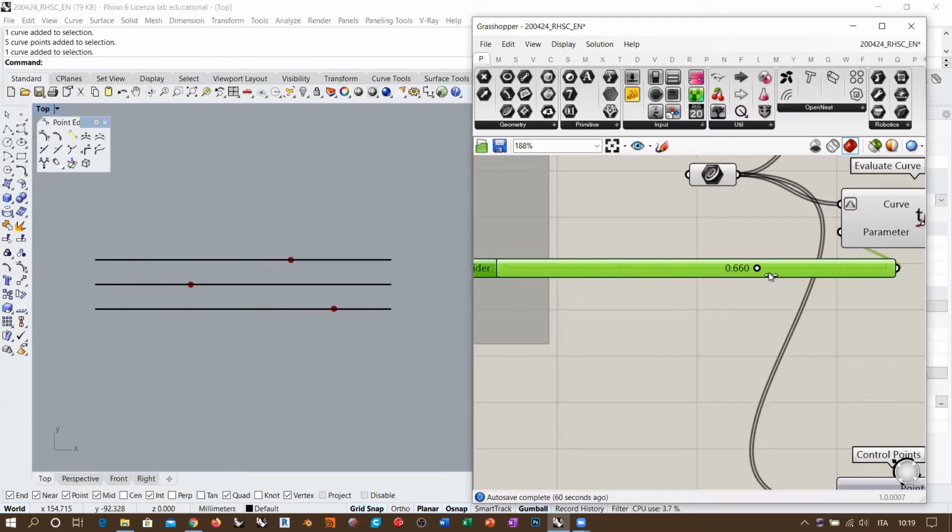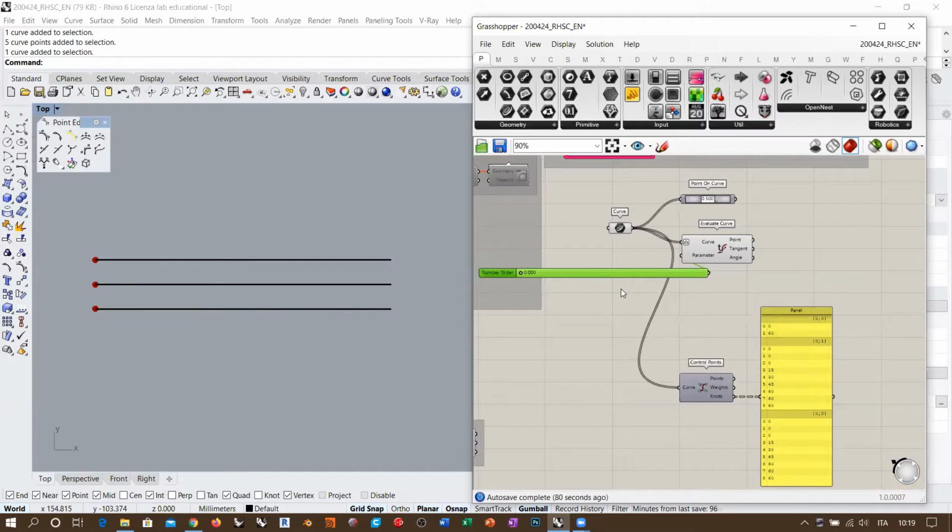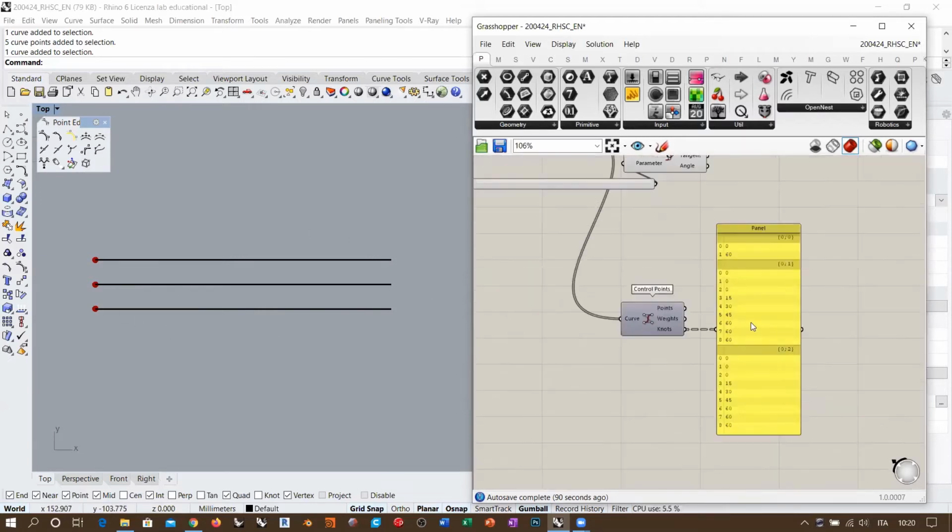And this is something that also helps you understand what happens when you create, for example, a sweep to rail, and the cross isocurves start to flow with some inclination. That inclination depends on the speed of the curve, which is represented by the density of control points and the density of knots and spans. So you always have a normalized distribution of knot values, of parameter values, but it doesn't mean that the length of the span is identical, because it depends on the concentration of control points.